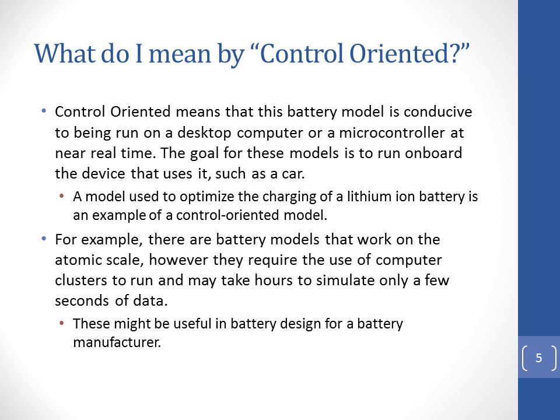The last question I want to answer is, what do I mean by control-oriented? It sounds quite exotic, but it isn't at all. The answer is that this model can run on a personal computer or microcontroller, such as an Arduino, in real time or even faster. I have 2 examples of this. First, for my own thesis, I want to optimize the charge pattern of a battery, so I need a battery model that can run very quickly on my personal computer. Secondly, for onboard a hybrid car, there might be a battery model running to estimate the lifetime left of the battery cells in the car.